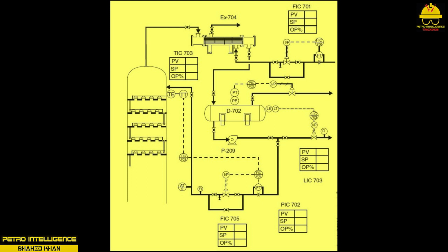74 gallons per minute of 98% butane is sent to TK710 in the tank farm. A pressure control loop, PIC702, regulates the pressure on the overhead system at 100 psi. Some minor butane loss occurs through this system. Excess vapors are directed into a flare header system.